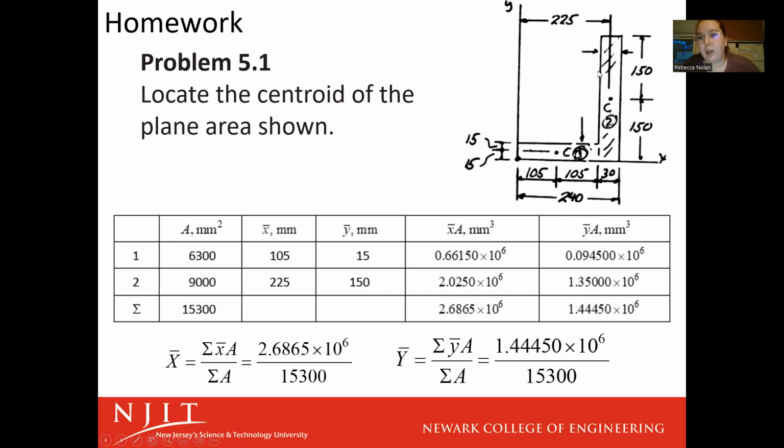It's always going to be with respect to the origin point, and not with respect to the start of the shape or anything like that. So that's how we get 225 for our x bar, and then y bar is a little more obvious, probably, that it's 300 high, so halfway through that is 150. From there, you put it in your formula and it's arithmetic, right?